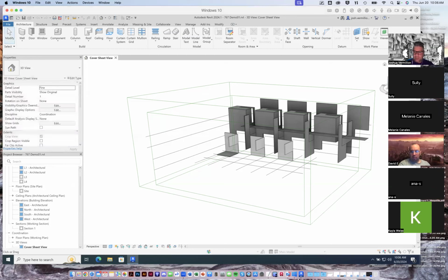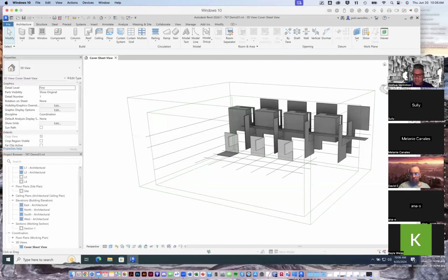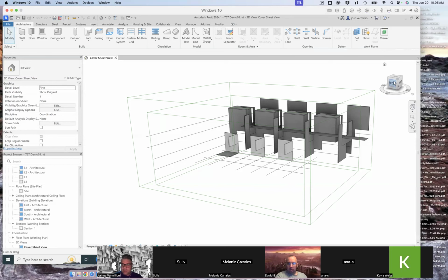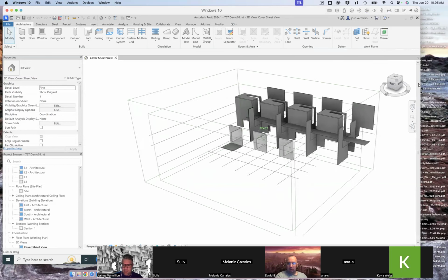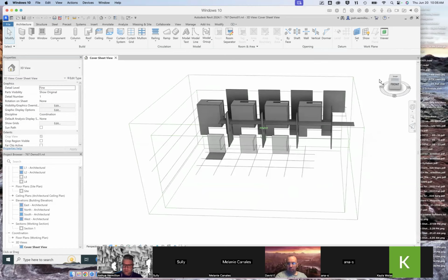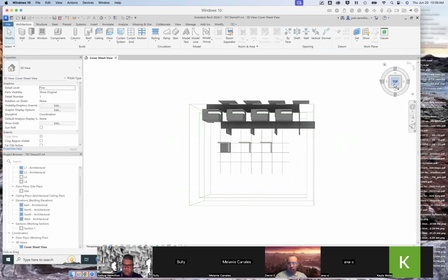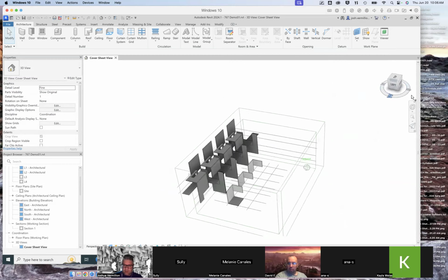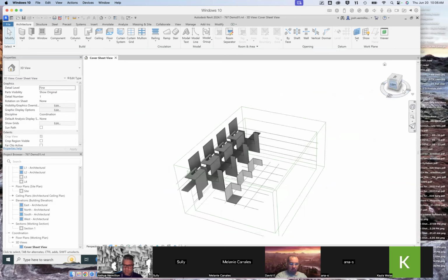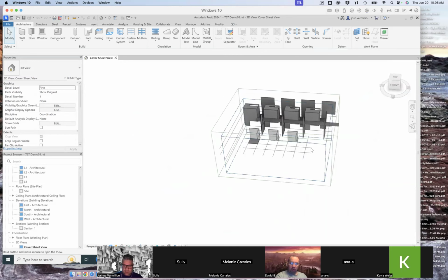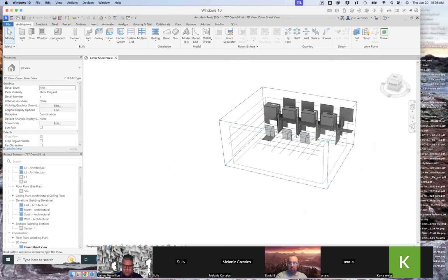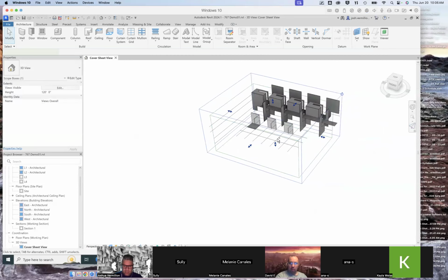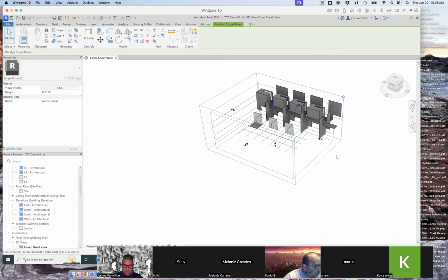Of course, let me just try to move this out of the way. See if I can move it towards the bottom. There we go. You can see there's a sort of block here with a compass, and you can begin to toggle back and forth between views. Like I can say top view, let's go to a corner view. Now I'm in perspective, looking at it from the left and front. I could, of course, just drag this compass around. If I hold down the Shift key and use the right mouse button, I can spin the view, or dolly or tumble.